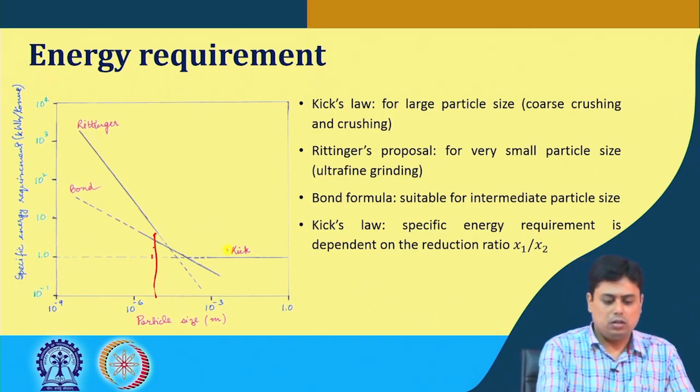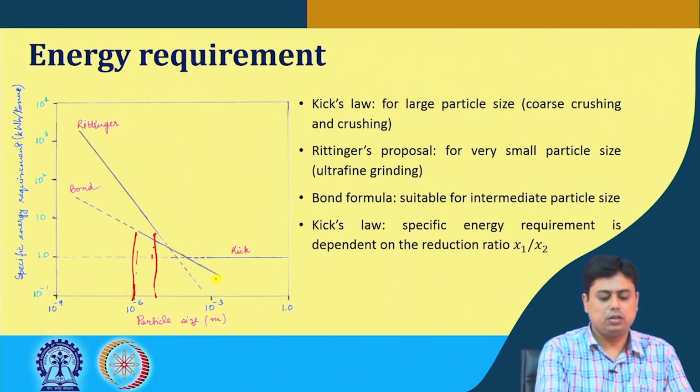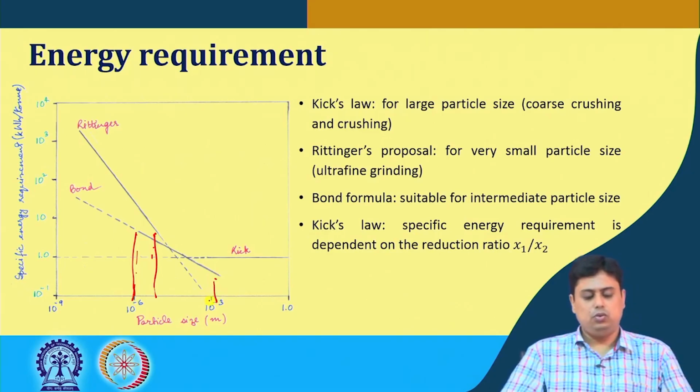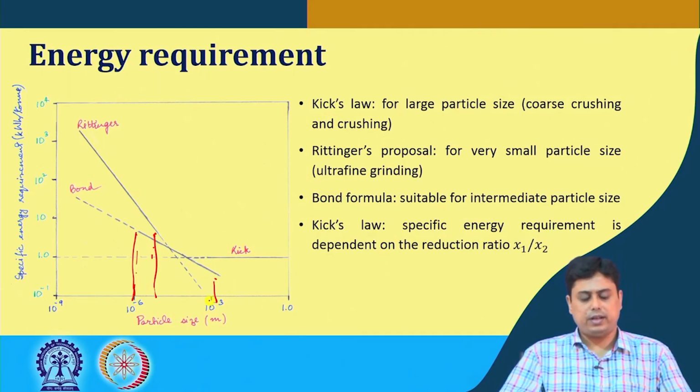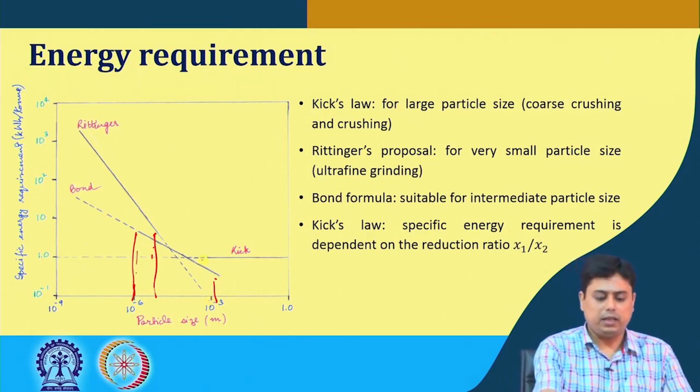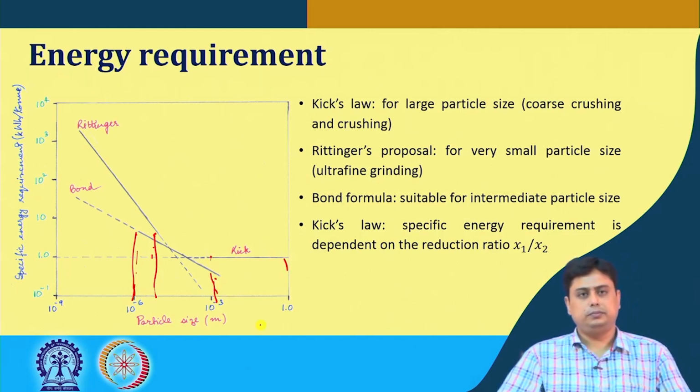Bond's law works from about the micron range to the 100 micron range, very satisfactorily. And for the coarse particles, we have Kick's law.